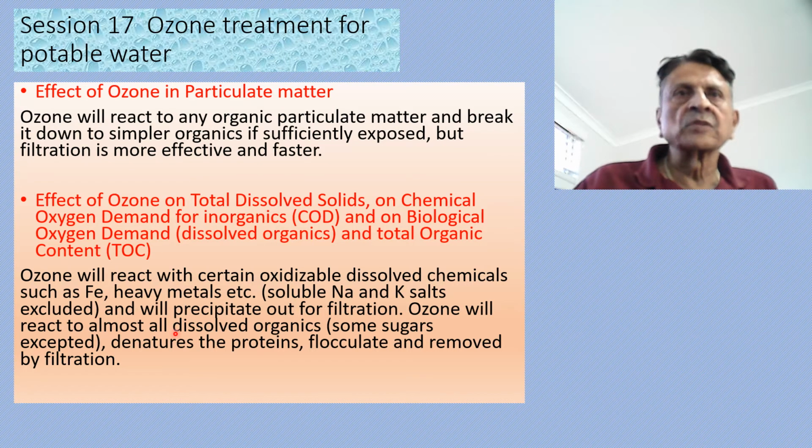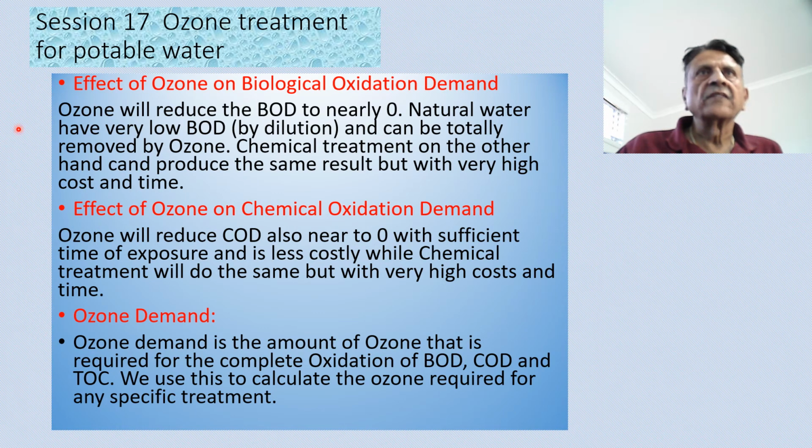Ozone will react with almost all dissolved organics, some sugars and small molecules of sugars excepted. It denatures the proteins by changing the nature of the protein and therefore its solubility, resulting in the flocculation and removal by filtration. The effect on the biological oxygen demand: ozone will reduce the BOD to nearly zero.